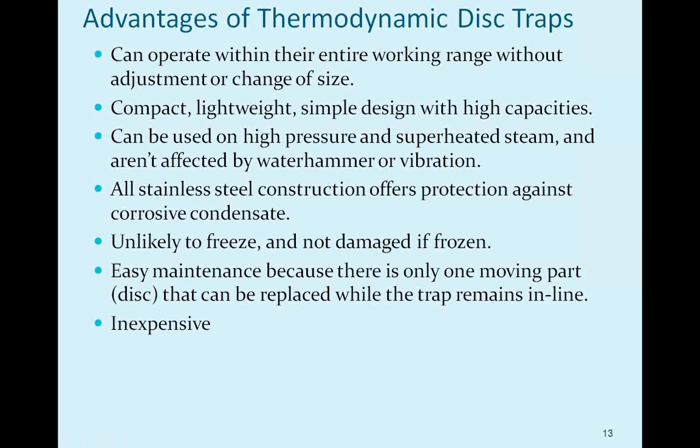Some of the advantages of these: they can operate within their entire working range without adjustment or change of size. They're very rugged. They're compact, very lightweight, simple design, and very cost effective. They can be used on high pressure and superheated steam. Water hammer and vibration really don't have much of an impact on these traps.